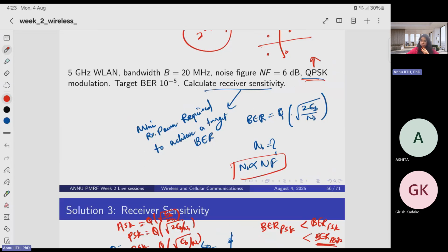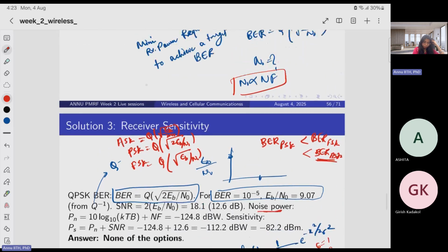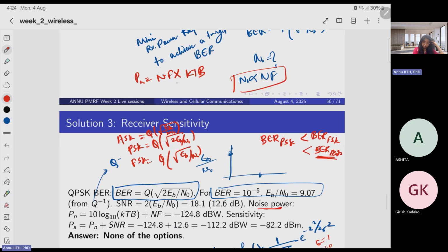Okay. The ideal noise figure is around 5, 6 dB. A lower noise figure indicates that a device adds less noise because it is proportional, right? It is a unitless quantity. That's why in dB, it degrades the SNR. So in linear scale, Pn is equal to the noise figure multiplied with KTB. In dB, it is plus, right?